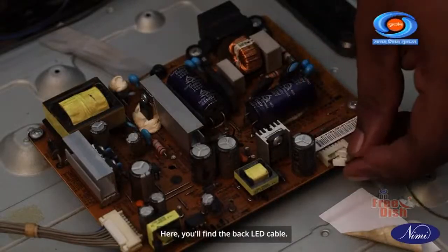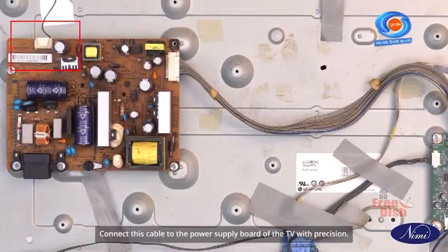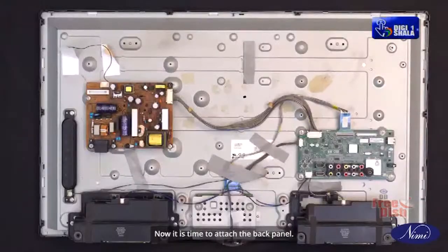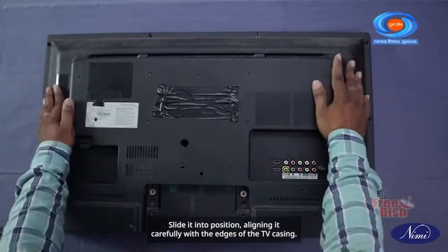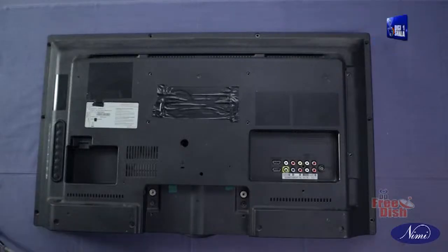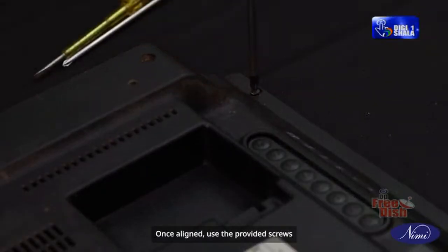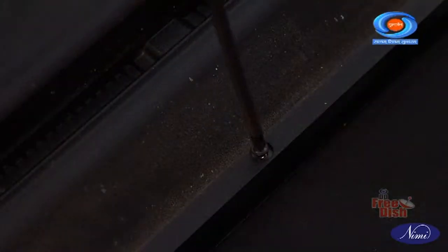Here, you will find the back LED cable. Connect this cable to the power supply board of the TV with precision. Now it is time to attach the back panel. Slide it into position, aligning it carefully with the edges of the TV casing. Once aligned, use the provided screws to secure the back panel firmly in place.